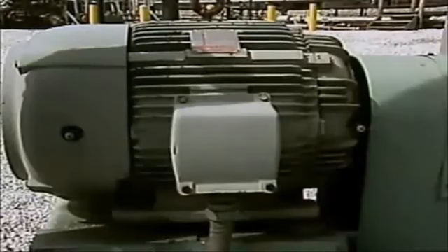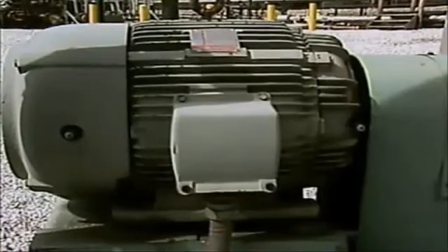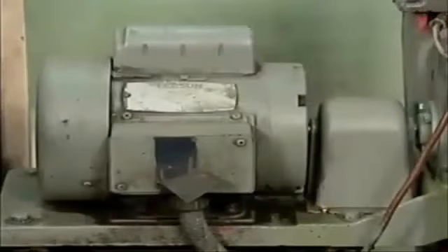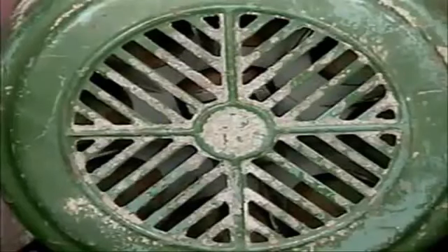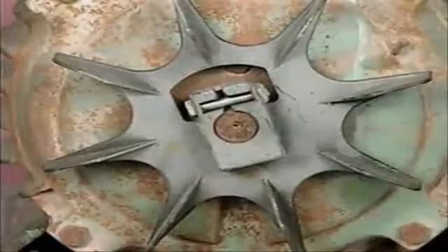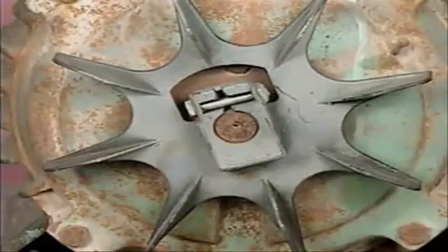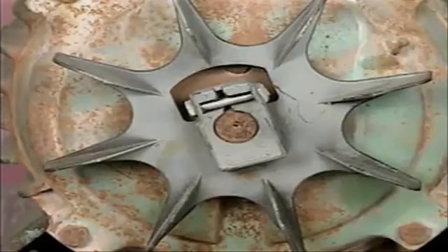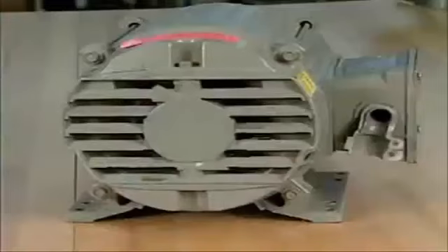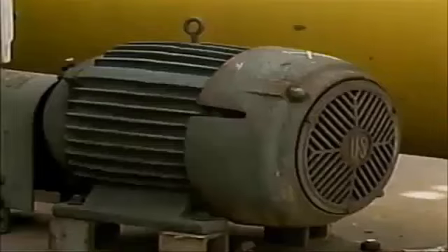During normal operation, an AC motor produces heat as a result of current flowing through it. Many motors use fans and ventilation openings to get rid of heat. On this particular motor, the shroud has openings to admit air into the motor to cool it. A fan cools the motor by pulling in air through ventilation openings in the shroud. As air is blown across the motor frame, the air carries away heat produced by the motor. Smaller motors may be cooled by simply letting heat escape from the motor frame. Other designs are also used to remove heat. For example, this motor has a set of fins.